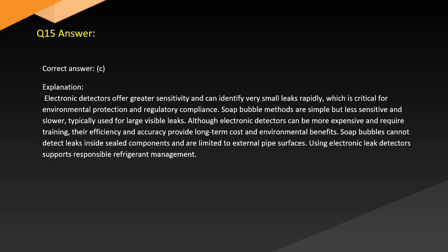Although electronic detectors can be more expensive and require training, their efficiency and accuracy provide long-term cost and environmental benefit. Soap bubbles cannot detect leaks inside sealed components and are limited to external pipe surfaces. Using electronic leak detectors supports responsible refrigerant management.